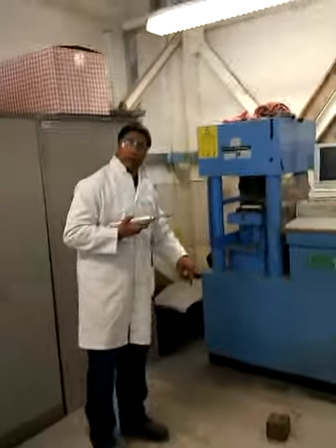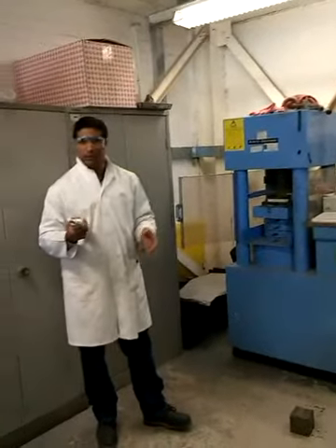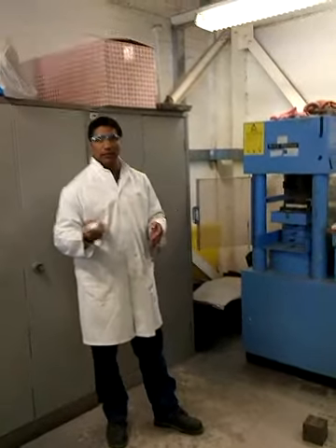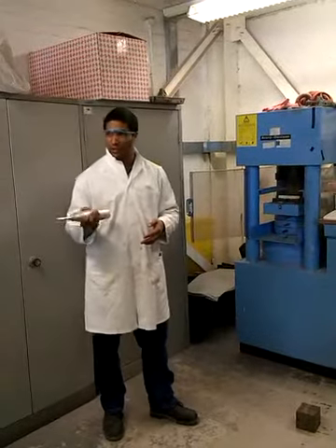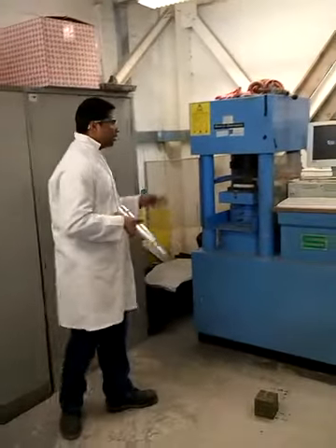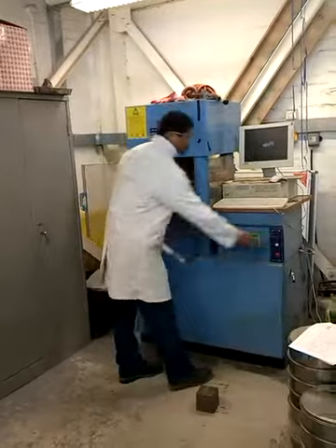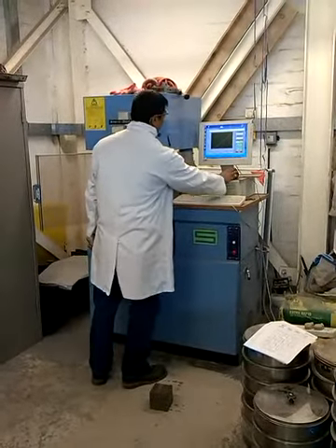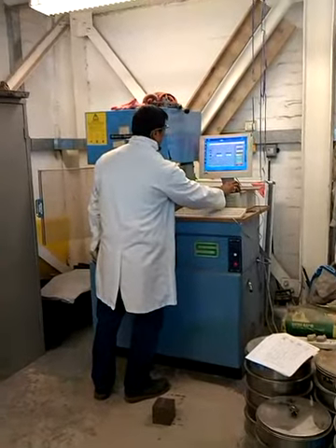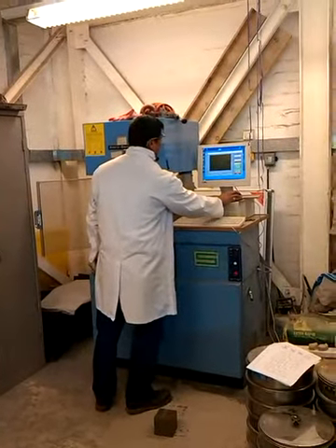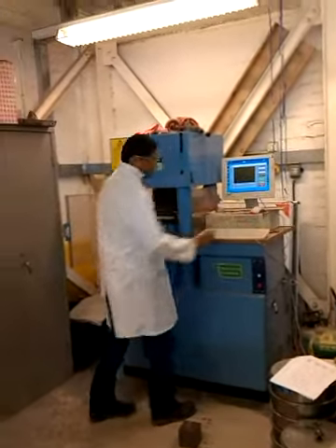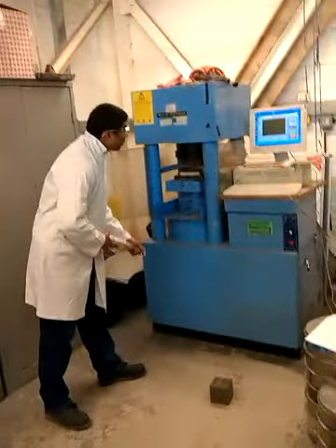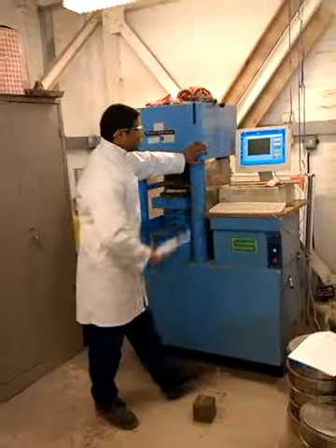These tests are being done at 14 days, which may be around 60 to 70% of the 28 days strength of the concrete. We will see what the strength is then. At the same time, I will give you 3 readings for this one as well. Once it is fixed, we will get some readings.